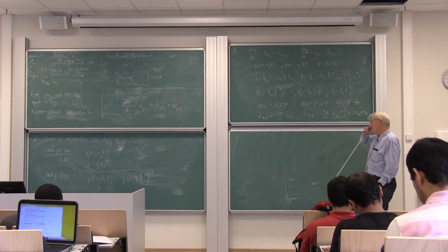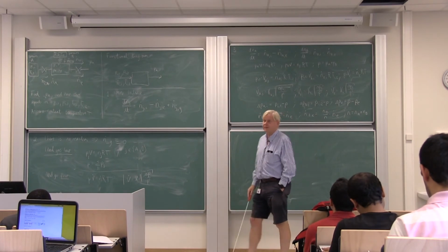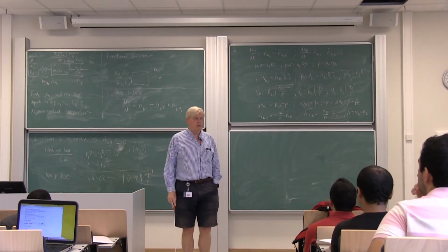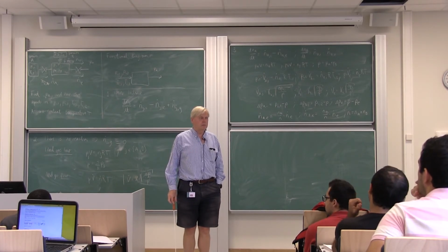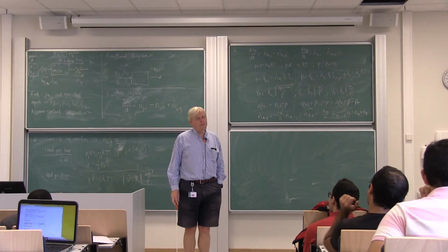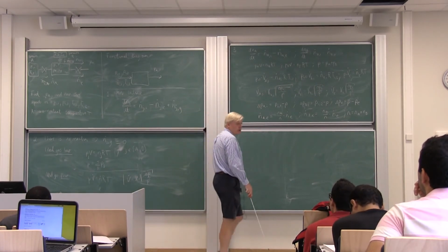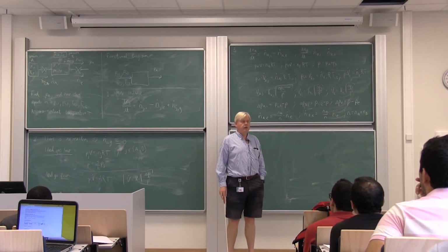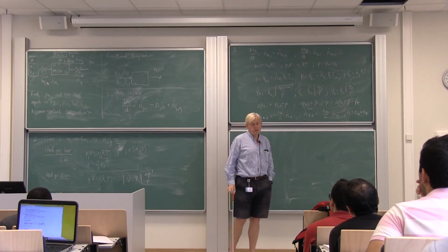If we instead use the DAE formulation, you have relatively many equations, but they are in general simple, and very little manipulation is involved. So typically to formulate DAEs is less work because you avoid the manipulation. And to do the manipulation, you need to form these first anyway, typically.